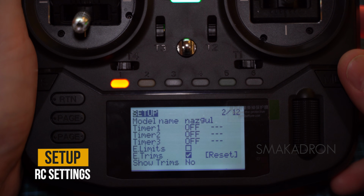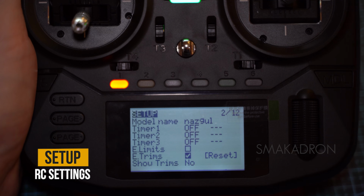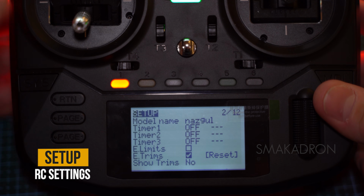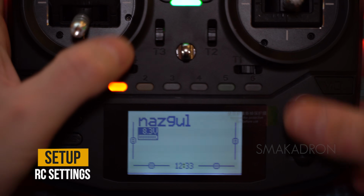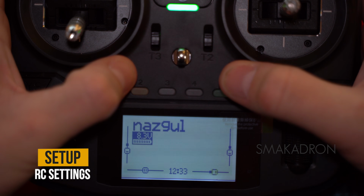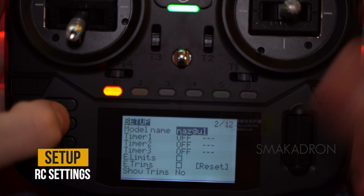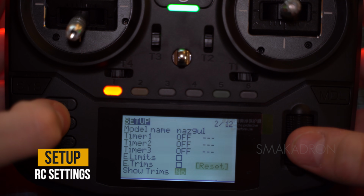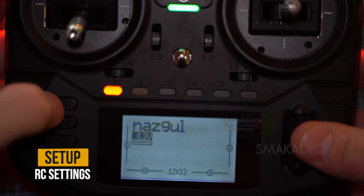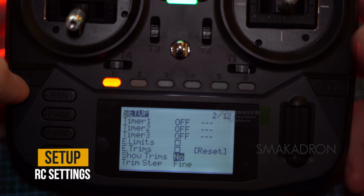Extended trims allow you to increase the maximum value of the trim settings from 25% to 100%. This helps you achieve more precise control of the model, especially if you need to make larger adjustments. Trims are the sliders that allow you to fine-tune the drone's control, but later I will explain why it's better not to use them at all and to disable them. Reset: if you press and hold the button, it resets all trim setting values to 0.